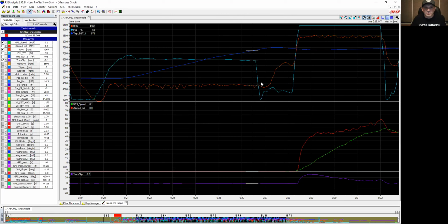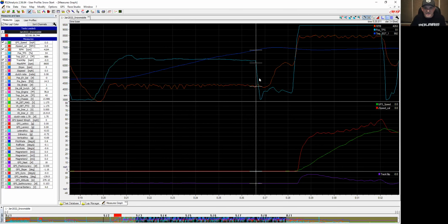Just how long the rider is on the hot start. You can see the blue line going up at a steady pace, up to probably 1100-ish Fahrenheit, about 50% throttle. You can see the RPMs are pretty consistent. And then he lets off, engages the clutch, and then you can really see where he's at on takeoff. RPM wise, that little dip right there, he's probably around 6,000-ish.